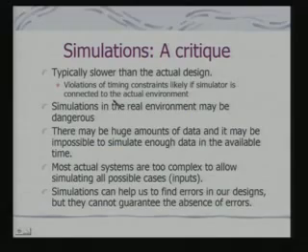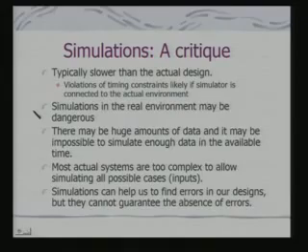So, simulations are typically slower than the actual design, and violations of timing constraints are likely if the simulator is connected to the actual environment. Okay, because simulation obviously means you are doing some kind of approximations, number one. Number two is you are also doing, to monitor the performance, some kind of management of the environment. That code which goes into management of the environment, that is housekeeping tasks, that itself can consume time, and so it is typically slower than the actual design.